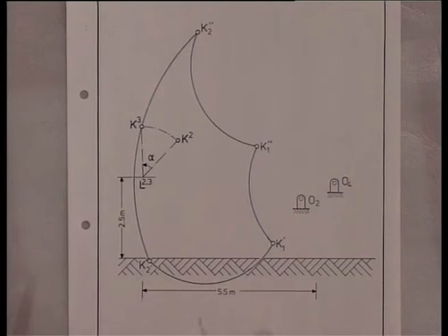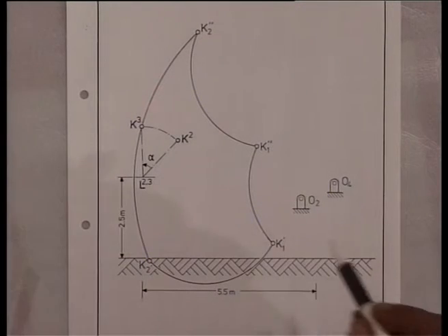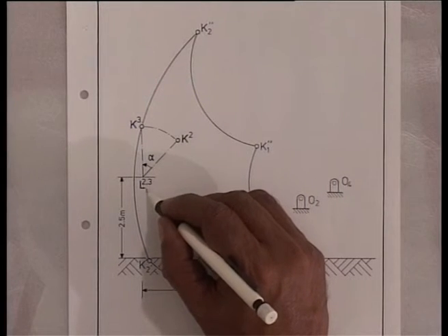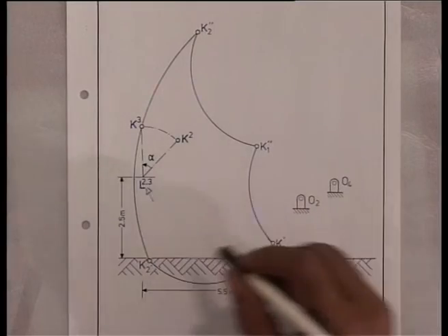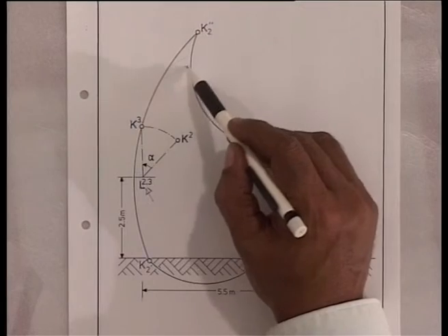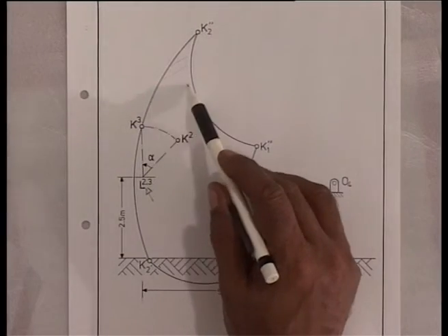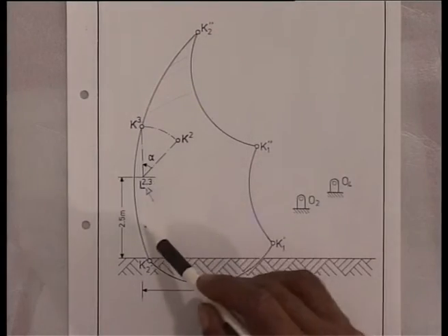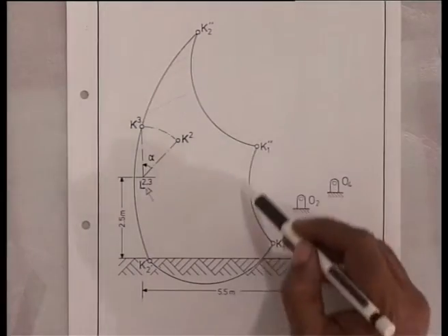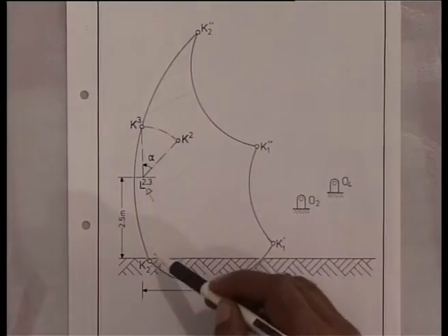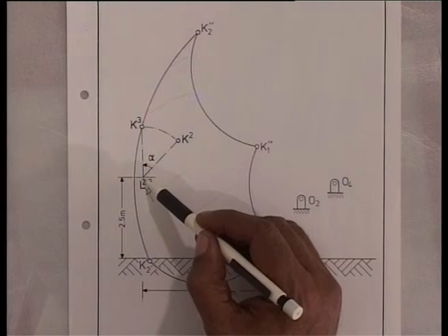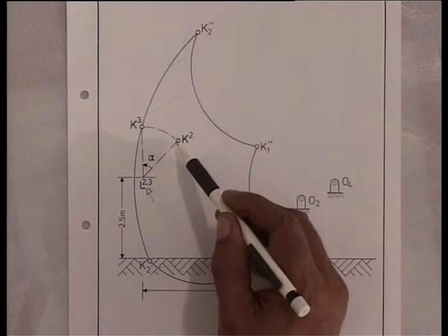To answer the third part of the problem, that is the tilt angle of the bin when the lip is kept at this location L2, we solve it as follows. We have already determined the region in which the hinge K lies when the total range of movements of the actuators are used. The hinge K can never go outside this region consisting of four circular arcs, but L and K are 2 points on the same rigid body. So, their distance cannot change.